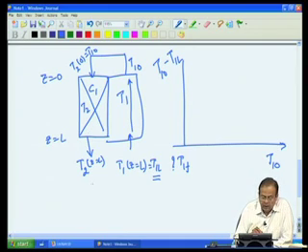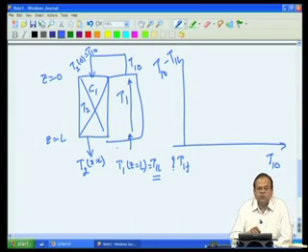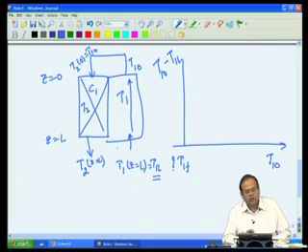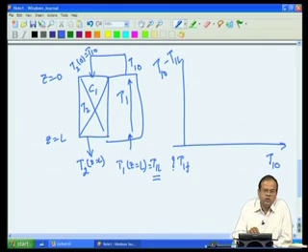So, my T1L, very little reaction means what? Very little heat generation. So, very little heat transferred to the shell. So, my T1 at this point will be pretty much close to T1 at Z equal to L, because there is very little reaction, there is no heat generation. So, no heat exchange or heat transfer which will preheat the reactant.